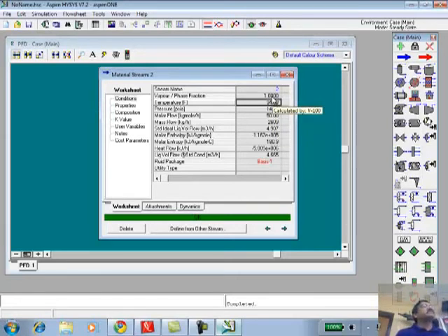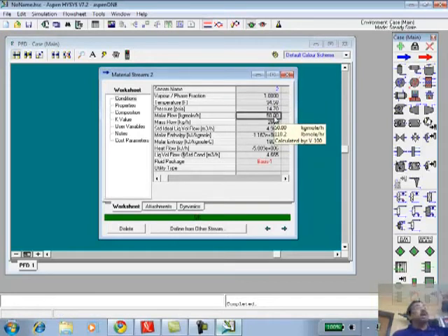Does it make sense? It does, because we have separated it out. All that comes to the top is in its vapor state under those conditions. But what should its flow rate be? Half of it. And there you see the flow rate. We put in 100 kilogram mole per hour, we're getting 50 mole to the top, and we'll have 50 mole to the bottom. What should the K values be?